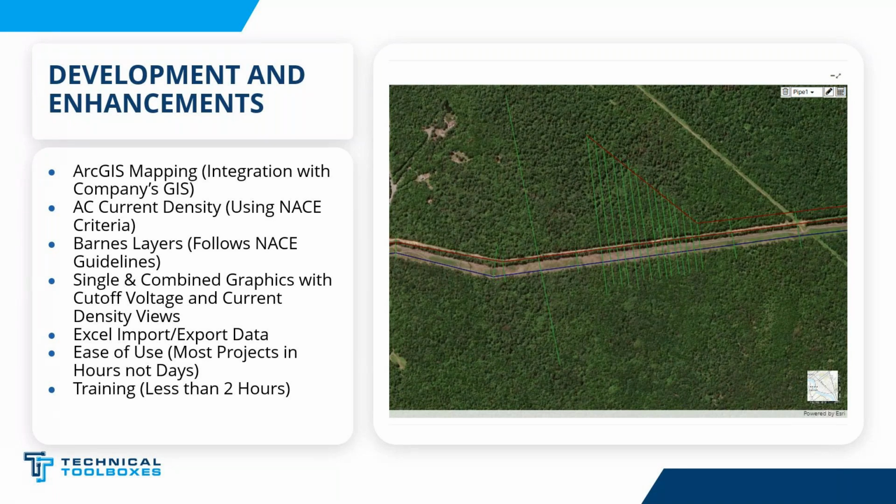If you want to do a 25, 30-mile line, you could click and point and put the sections where you want them, not where some other program says to put them. Based on the geometry, the resistivities, the transpositions, road crossings, whatever's there, or other construction restraints if you're going to build an AC mitigation.